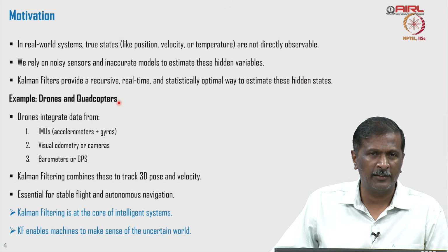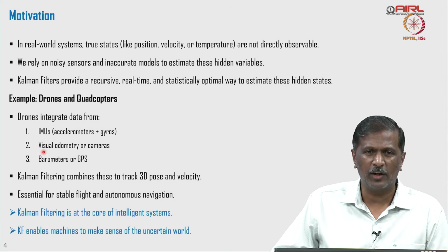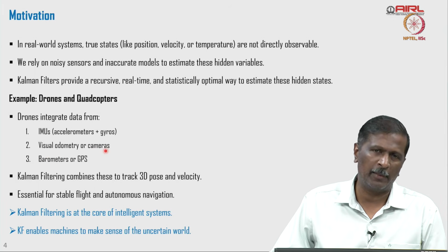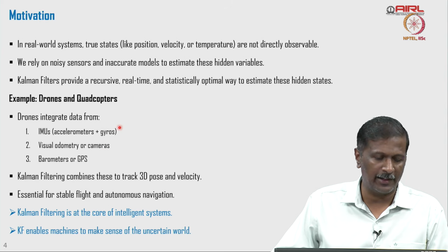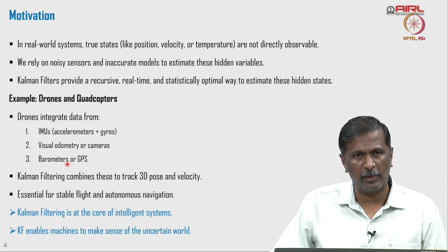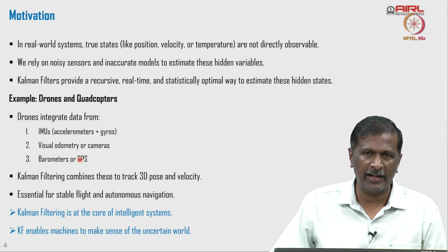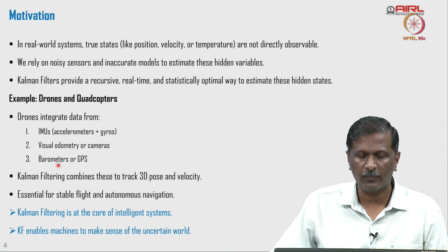For example, in a multi-copter system, we integrate inertial measurement unit, IMU, data. We also combine it with visual odometry or camera, or what I meant, an optical flow sensor, which can be used to collect the data. Sometimes we can use a barometer, LiDAR or radar to get my height, and I can combine all of this to get the states of the system.